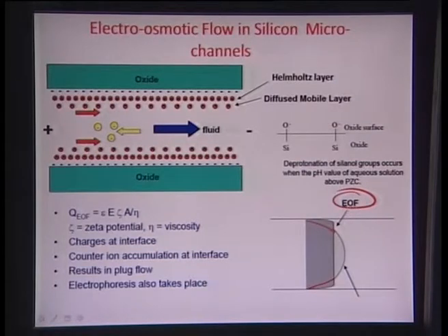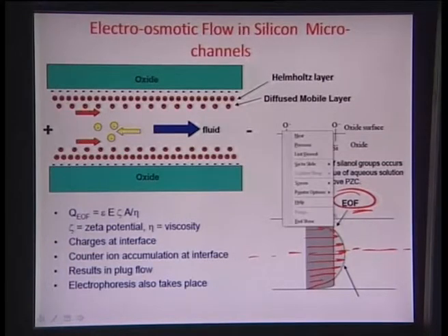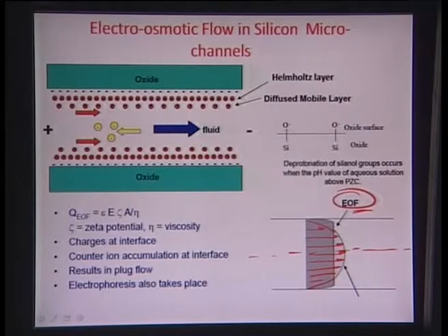So, the velocity vectors keep on increasing as they go from the walls towards the center of this particular capillary. On the other hand, for the EOF or the electroosmotic flow, as we know, the flow takes place as a plug flow from the start of one double layer, which is essentially this side here, all the way up to the other double layer on the other side of the channel. So, this area has a constant velocity, right.